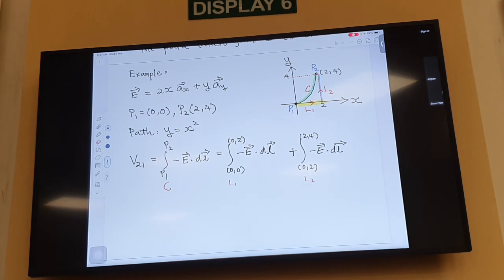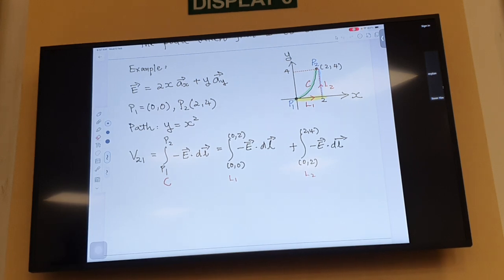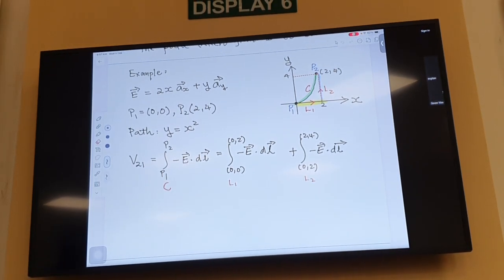So then the next question is, which point is higher potential? If you look at it very straight, I cannot say A or B, it looks the same when you rotate it here and there. Anyone can answer this one? If I put a voltmeter here, what is the reading of the voltmeter? You see, this is 1 ohm, correct? 1 amp, because the 2 ohm divided gives this 1 ohm, so 1 times 1 is 1 volt.